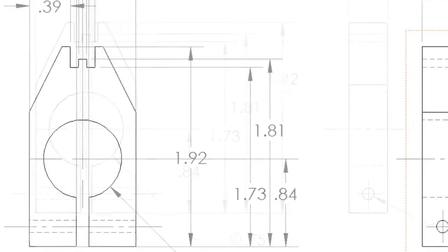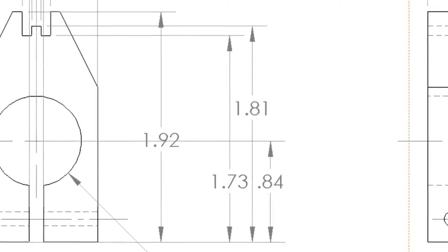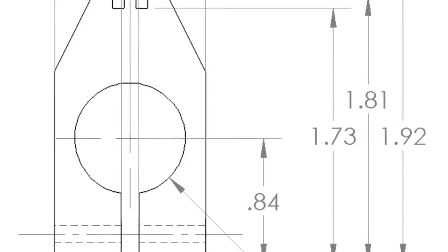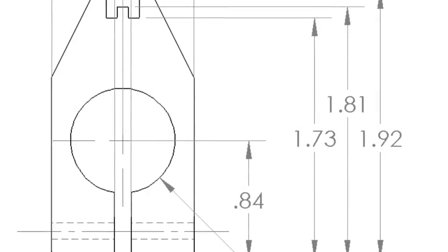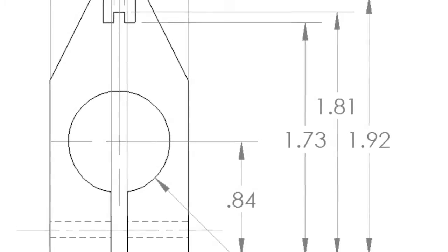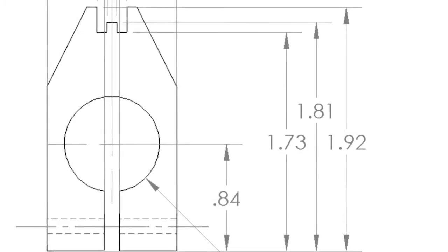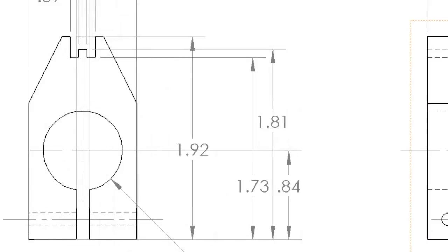Dimensions should be placed in an order which reduces the crossing of extension lines. When small dimensions are placed the closest to the part, with larger dimensions being placed farther away, there is little, if any, crossing of extension lines. This placement promotes clarity and organization, while mixing the placement of dimensions causes lines to cross and is unclear.